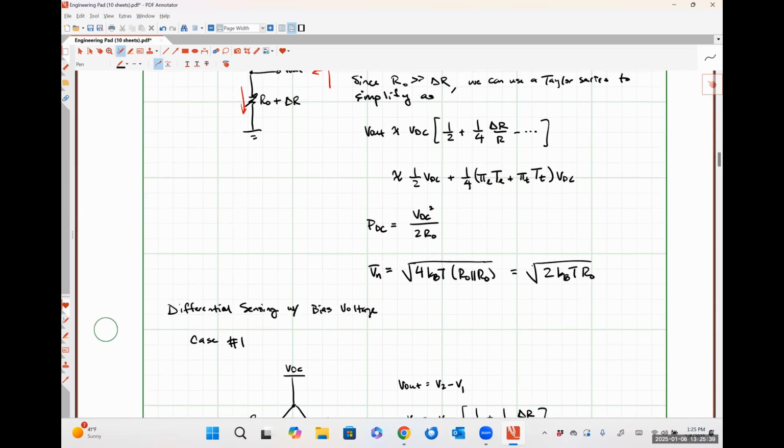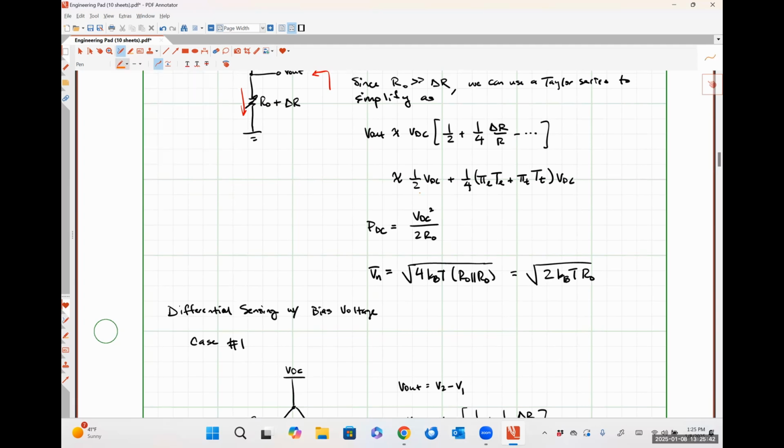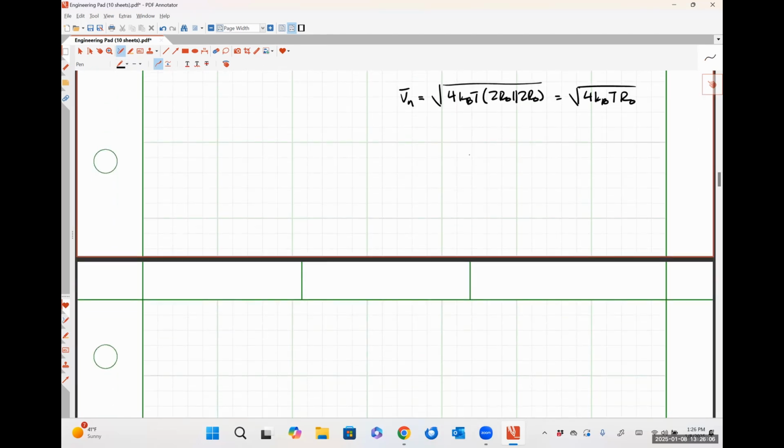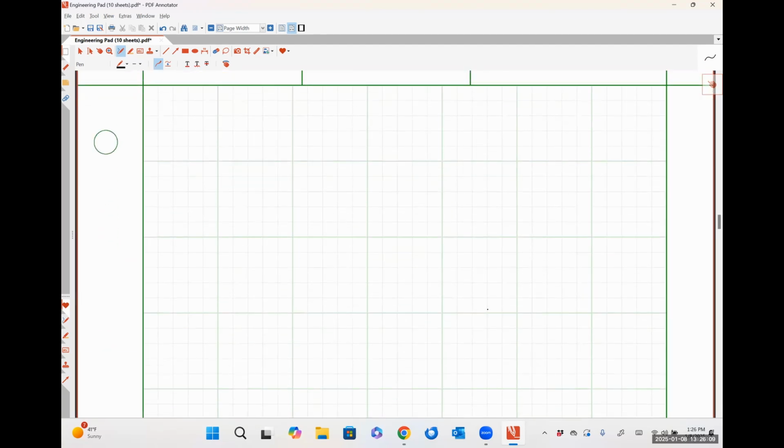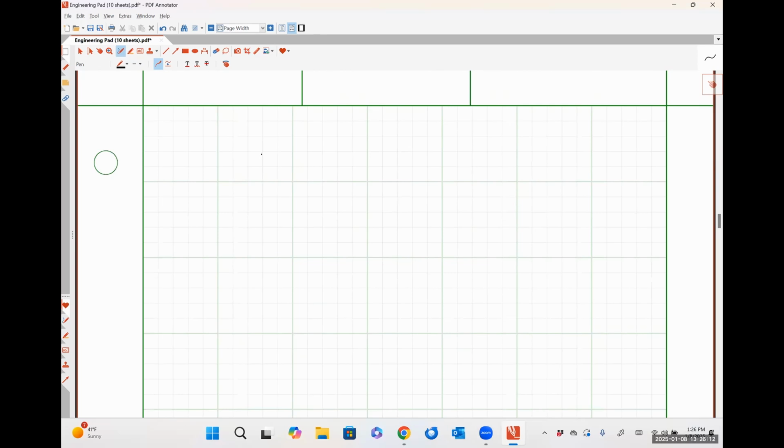Is it more sensitive? So the single-sided sensing contains a DC term. So we have a DC signal that, if we need to amplify our output, is also being amplified. I don't know how familiar you are with electronic amplification. So let me just do a quick aside here. Let me go several pages down, okay? Let's just say that we're going to amplify our signal using an op amp, which is the most common way to amplify literally any electrical signal, okay?